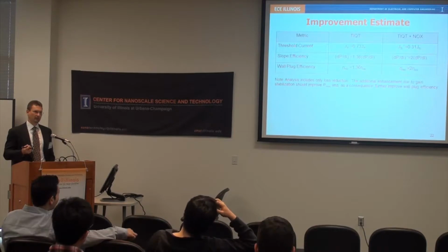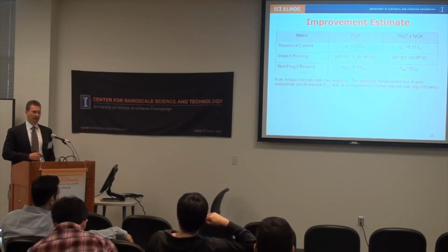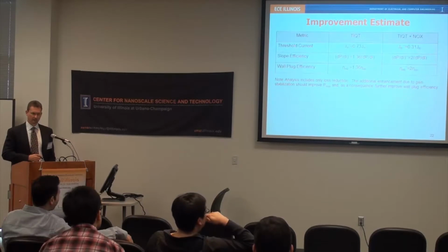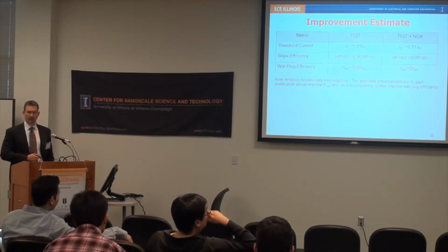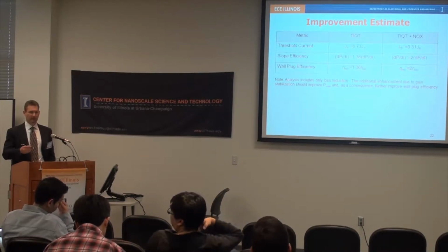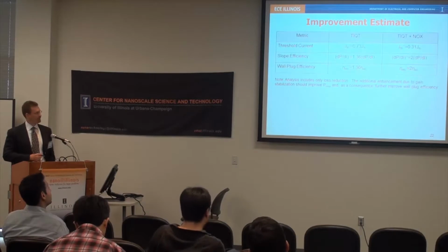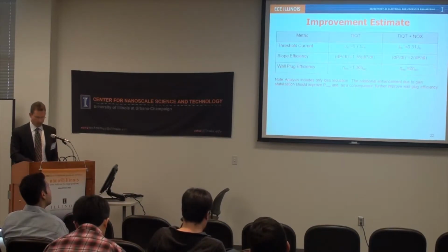and looking at the overlap of those modes with the doped material in the structure, and in particular, the P-type material is problematic because there's not a lot of data in the literature right now on mid-IR absorption for lightly doped P-type material. So we're having to do some estimates based upon the data that is available. But again, we think that these are reasonable and what could be expected for this sort of device.